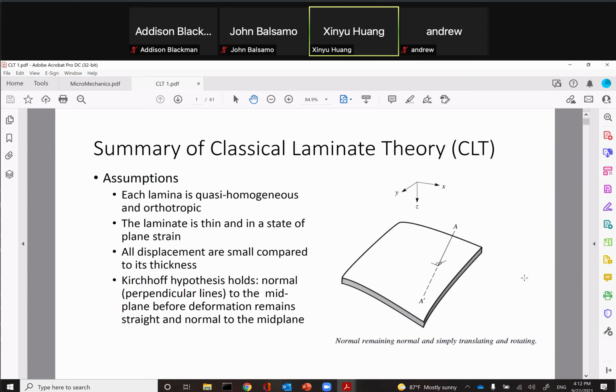Yeah, there's something called neutral axis, right? And their cross section. There's an assumption actually. The fundamental, the basic beam theory has an assumption that the cross section perpendicular to the neutral axis remains planar after deformation. It doesn't warp. That's the fundamental assumption that goes into the beam theory. That basically results in everything you learn after.